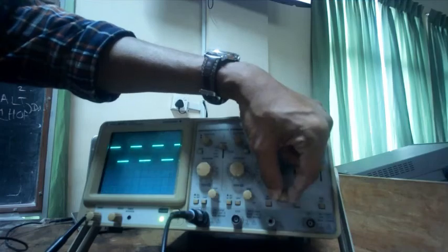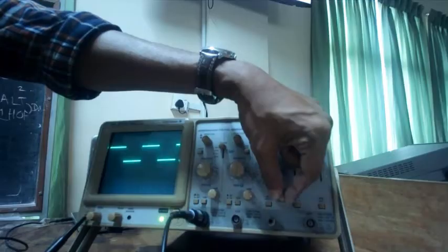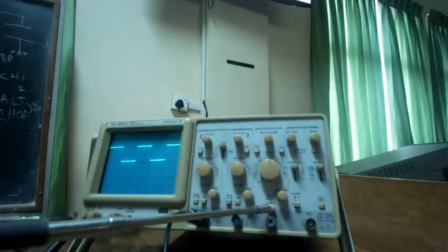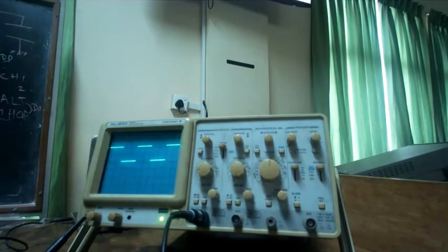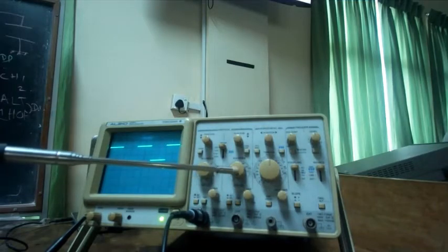Now the signal has not changed, but I can change the time base, right? So what that means is, if you take it out of calibration mode, you cannot use this dial to figure out what exactly is the time per division setting, right? Is it clear? So in order to make time measurements, now earlier I said if you are making voltage measurements, you have to ensure calibration position is there in the vertical commands, vertical channels.